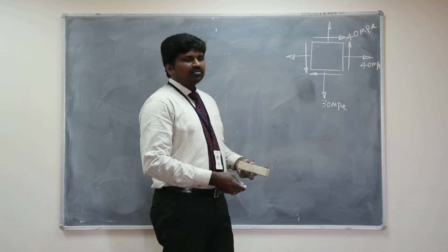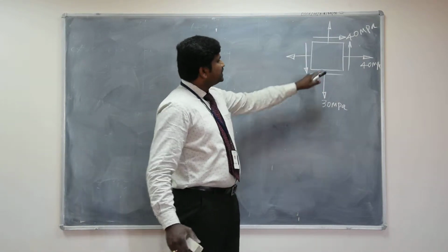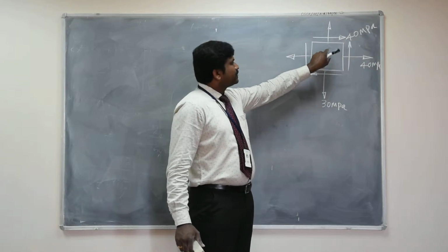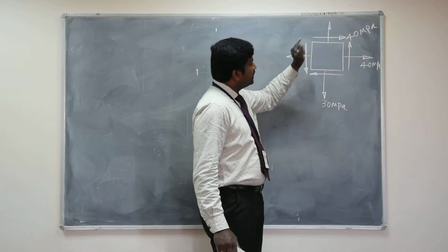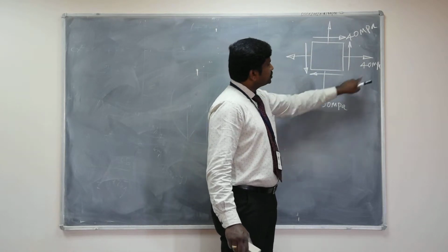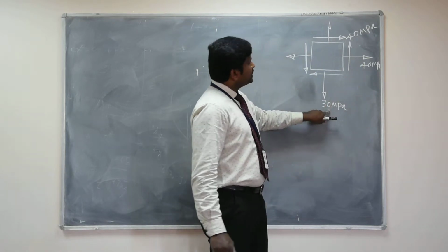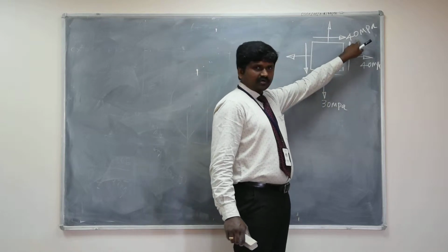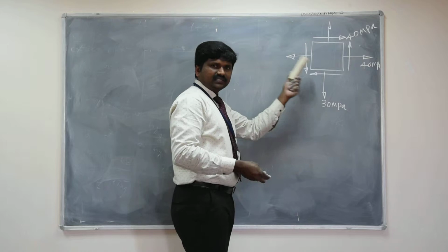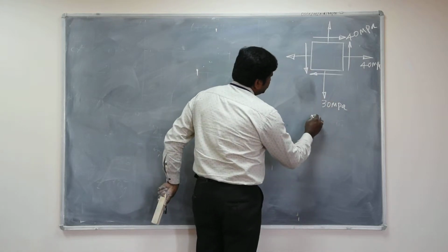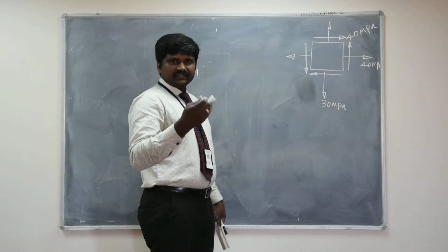Yeah, to understand the Mohr circle in detail, let us solve one numerical example. In this numerical example, this is a two-dimensional stressed element subjected to two normal stresses, 40 MPa tensile, 30 MPa tensile, and the shear stress 40 MPa. So the aim is like this. Given this stressed element, we need to find out the magnitude and direction of the principal